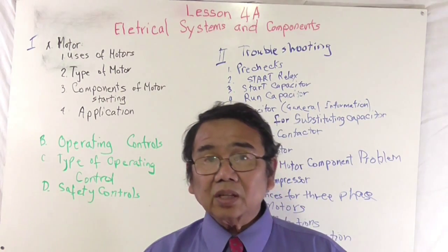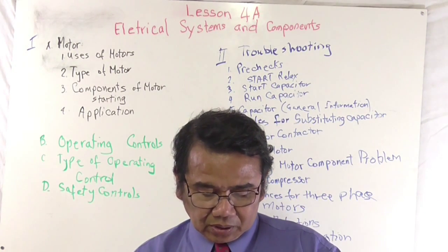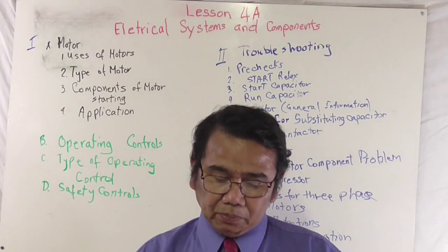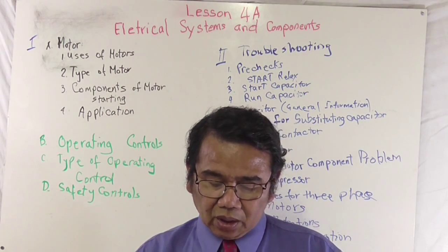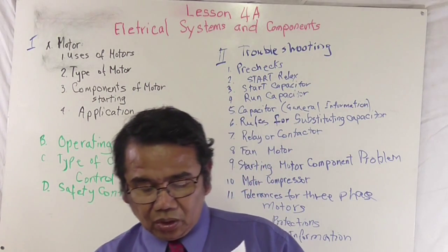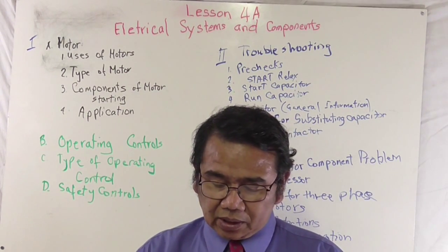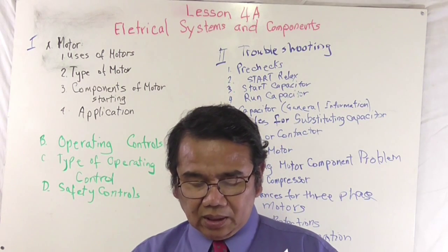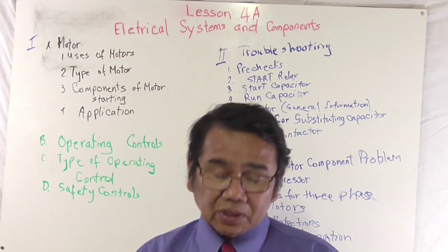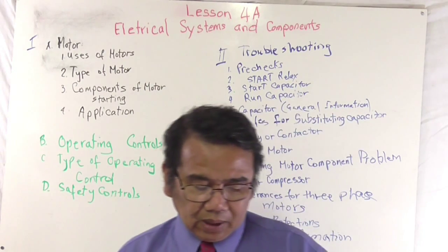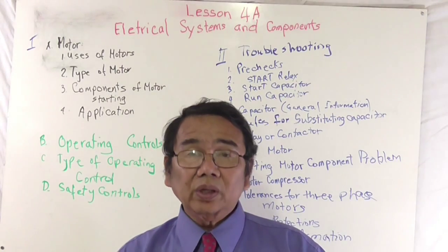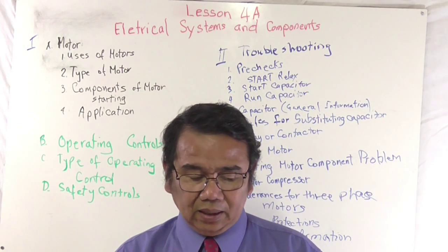And then you've got starting capacitor shorted. It will draw high amperage and the internal protector will trip. Good possibility the start capacitor will blow up. Starting capacitor opens. The problem is the starting capacitor is open. The compressor will run like a PSC motor, if it were to start, okay.